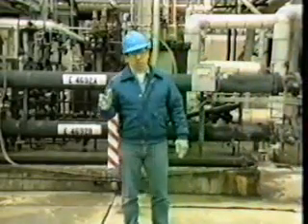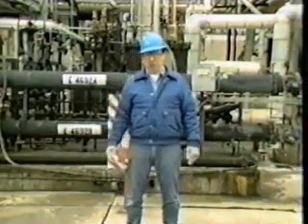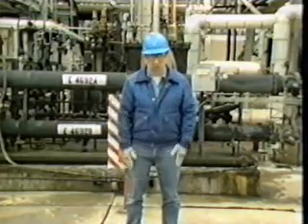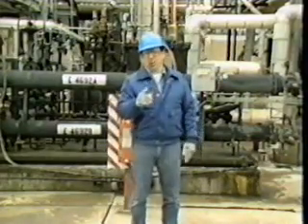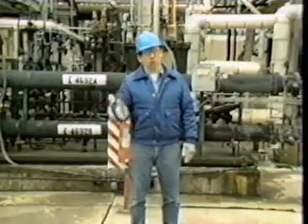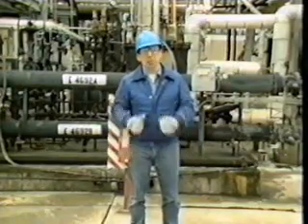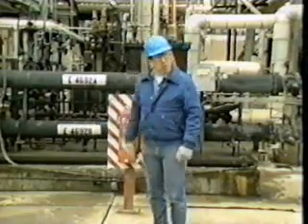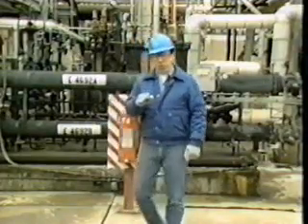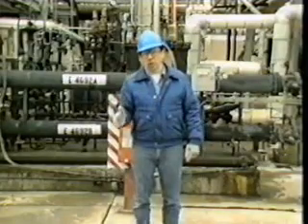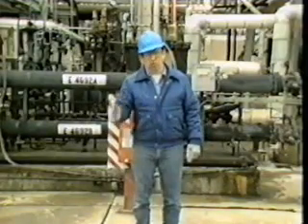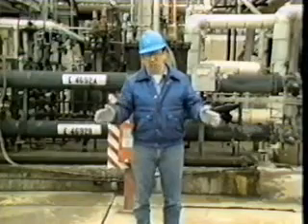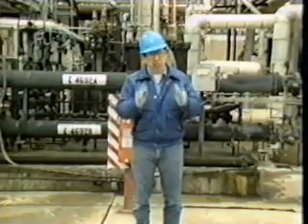Almost any large machine needs some type of lubrication, and the centrifugal compressor is no exception. Without the proper lubrication, frictional heat could build up to a dangerous level, possibly damaging the compressor. That's why lubrication systems are so important. Most centrifugal compressors use external lube oil circulation systems to lubricate and cool all bearings and gears in the compressor and accessory drivers.